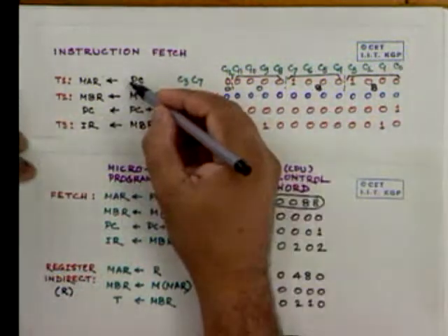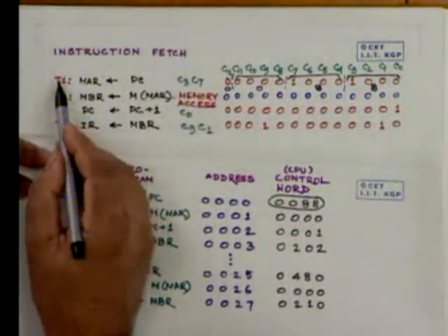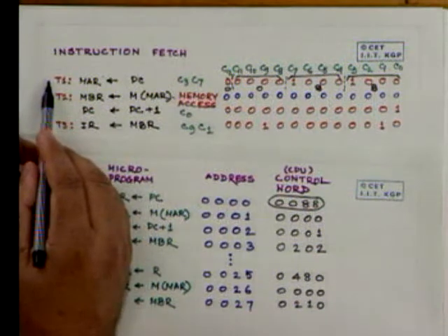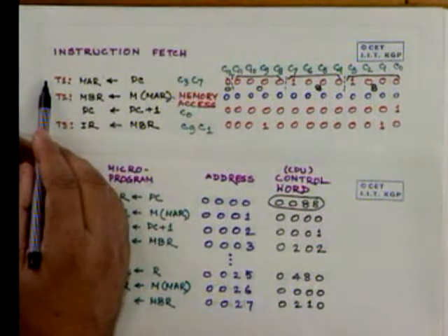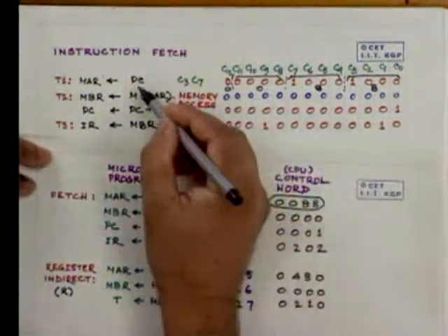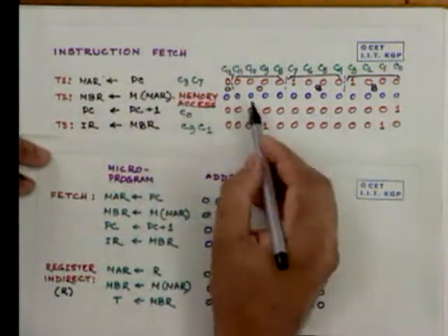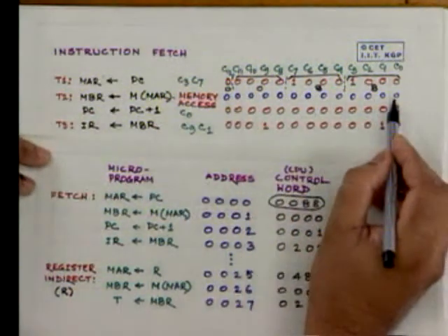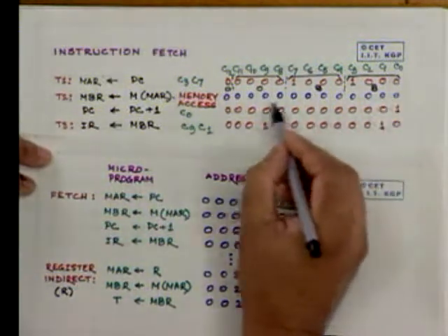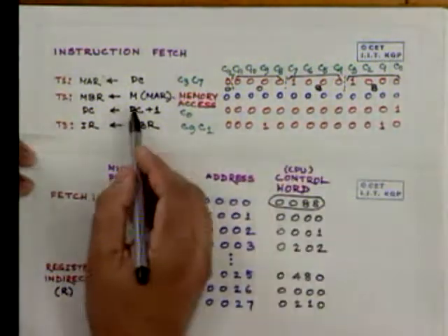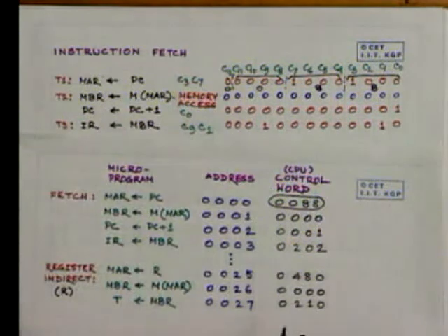After this is over, we can keep a program counter kind of thing. Then the program counter can be incremented to the next location, and this location can be read, and the next micro word can be executed, which means that the next micro instruction can be executed.